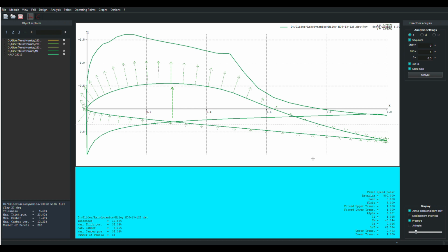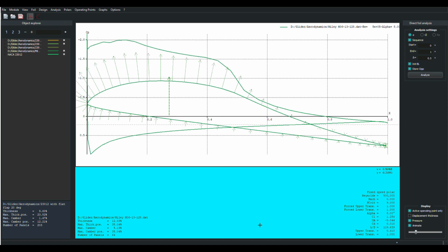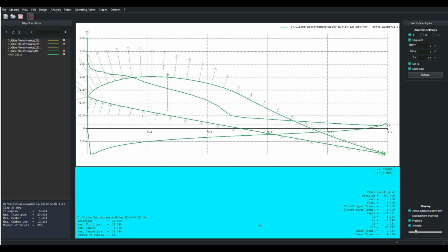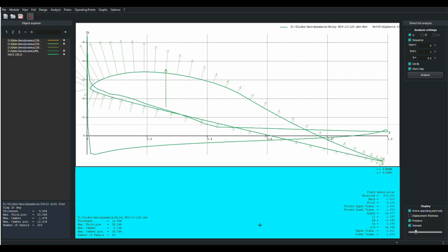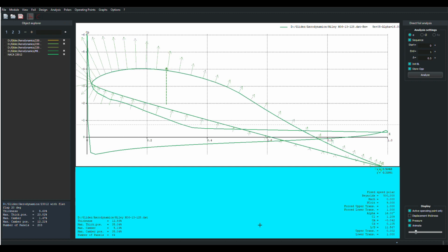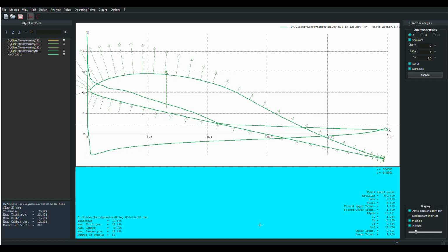And also because of the selection of the airfoil, probably, we'll say accidentally, just out of happenstance, it avoids this problem of generating a big pressure spike here. And I'm going to show you that in a minute when I deflect this guy, and we're going to go take a look at that case. But in the meantime, let's just animate this and watch it go through its angles of attack and watch the pressure distribution and how it behaves as we go to high angles of attack. And then we come back.